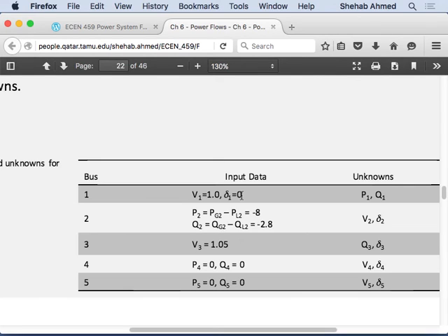Again, this is just from a practical perspective. For our cases, we will always have slack bus 1 and 0. We will always assume our angles start with 0 and our voltages start with 1, right? But practically, if you have a system that is stressed and you want to do a power flow analysis for that system, this is what you would do. You would not just start with it, because it's a guess. If the guess is bad, it will not converge. Okay, what, you sit down and wait? So you have to find a way to solve it. That means your guess is bad, so you have to find a better guess, and that's a way to find a better guess, right?